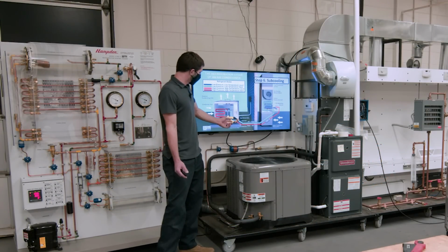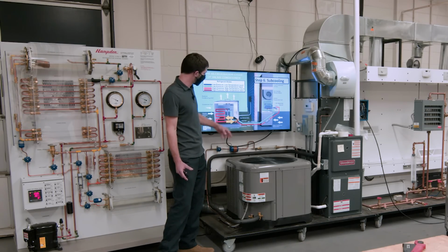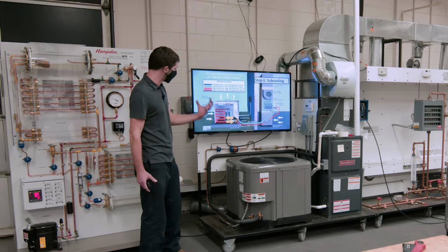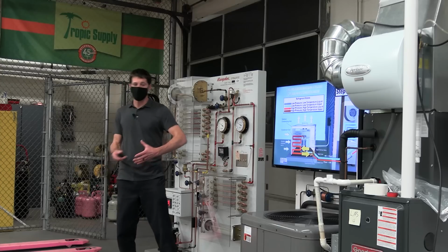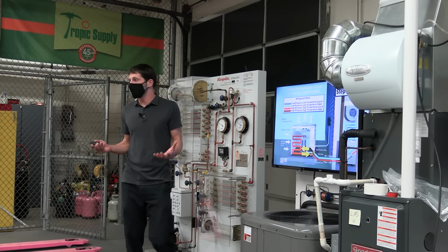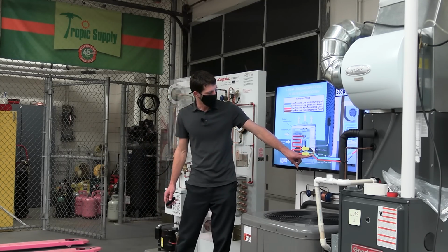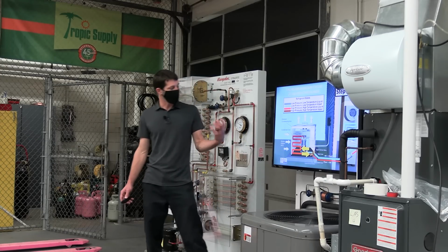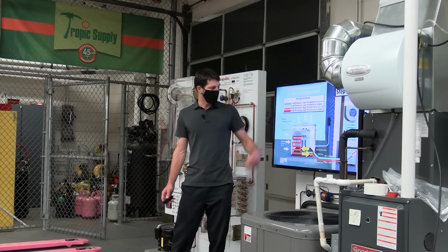You may ask, how do you measure that? Really, you just take a pressure measurement right here. You convert that to saturated temperature on your gauge face, using the Danfoss refrigerant slider app, a digital manifold gauge set, or any type of calculator you have on your phone. But basically, you're measuring your pressure at the port right here. You're converting that to saturated temperature for whatever refrigerant is inside this unit. You need to know that beforehand.